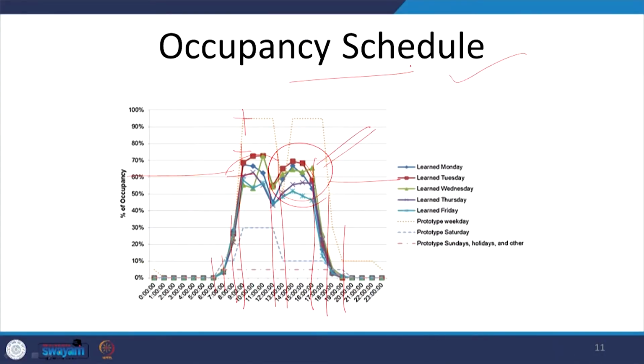Because occupants are not there, we have to assume based on this occupancy schedule; we can also schedule how the HVAC, mechanical ventilation and lighting would be functioning, thereby achieving energy savings through the active systems. So, occupancy schedule is very, very important, and on the basis of occupancy schedule many other schedules are also decided.